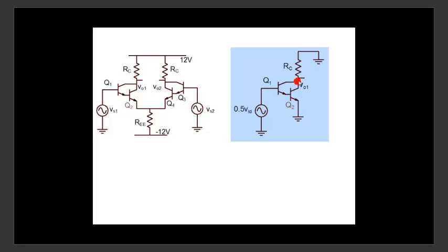If you want to find the gain at this point, one way, as we said, is to build the Norton's equivalent at this point. Convert the whole circuit here into Norton's, IN and RN. Break it down into two parts. Ask yourself, what is the net Norton's current at this point? What is the net Norton's resistance at this point? Then the voltage gain would be, note that V0 would be simply minus IN RN, divided by VS.